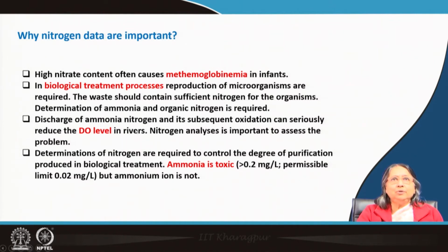Now, discharge of ammonia nitrogen and its subsequent oxidation can seriously reduce the DO level, that I already told you in BOD, okay. Nitrogen analysis is important to assess the problem, okay. Oxygen DO level should not go beyond some level, okay. Then anaerobic condition will be generated, that is not wanted, okay. Then determination of nitrogen is required to control the degree of purification produced in biological treatment. You all know this, very interesting.